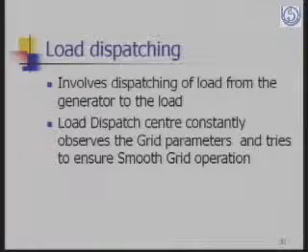So basically I will first start with load dispatching. Dispatching of load means dispatching of the generation to the load. Load dispatch center constantly observes the grid parameters and tries to maintain the grid parameters. As explained, the load dispatch center has the voltage of each line, the voltages being maintained at each substation, the currents drawn, the frequency maintained in the system, and the harmonics in the system.